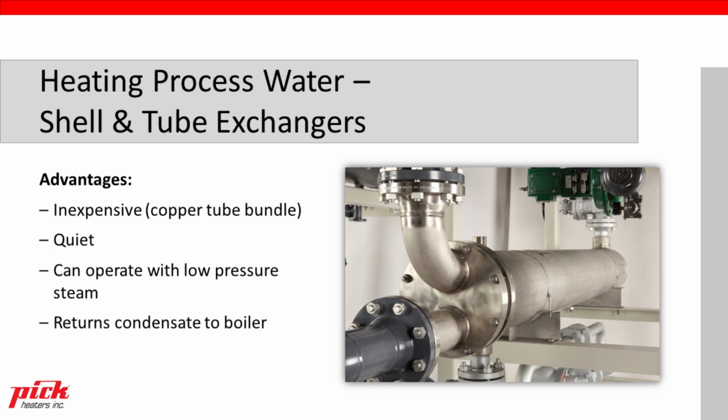Oftentimes they're sized for that 8 to 10 to 12 psi steam pressure range. They do have to get bigger because of that lower pressure steam, but they can handle that because the steam is not in direct contact with the water. And then lastly, once that steam condenses inside the heat exchanger, that condensate is returned back to the boiler for reheating.